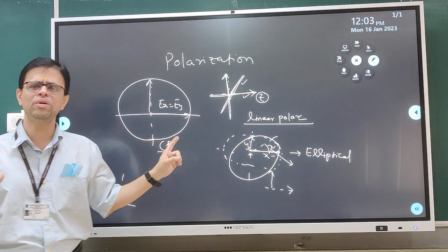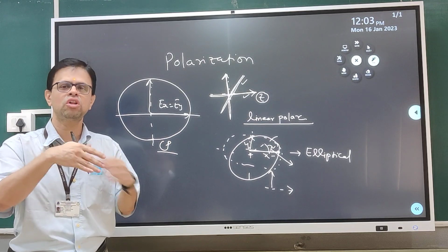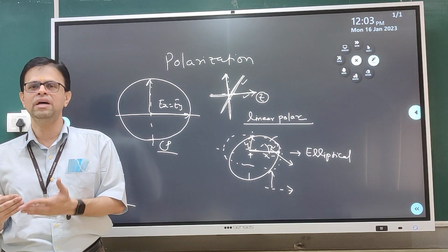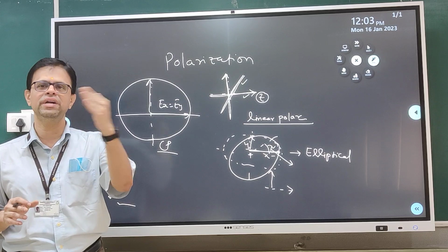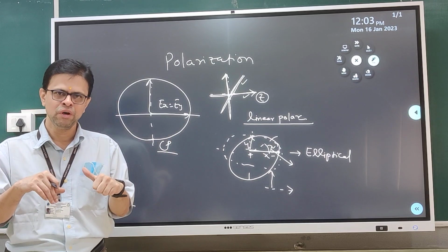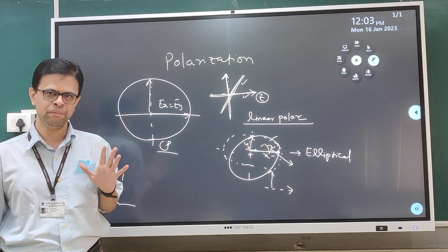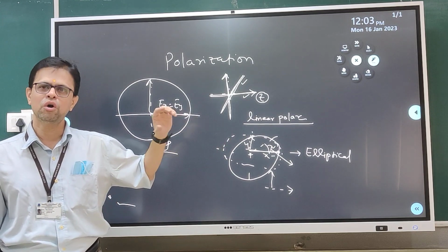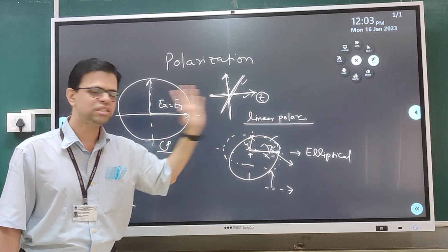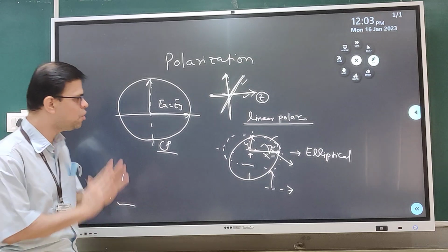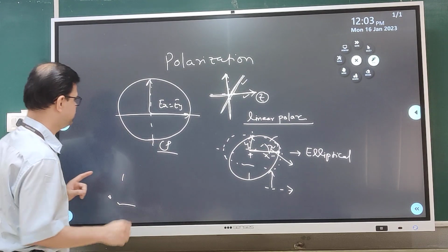I will also try to give a relation by looking at the surface current distribution or the aperture distribution of the antenna. One can judge what kind of radiation pattern, end fire or broadside, or low or high cross polar radiation pattern, will be obtained. So I will also try to relate the cross polar level with respect to elliptical polarization, linear polarization and circular polarization. Now I will talk about the conditions which realize circular polarization.